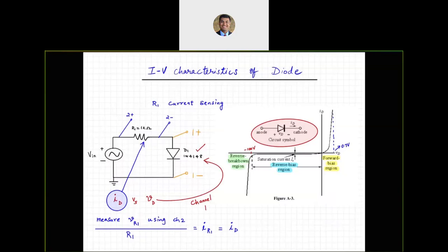The question is: subtract the threshold of the diode from the circuit's voltage, then calculate the current in the circuit using the remaining voltage. Yes, that's exactly right. So the turn-on voltage or the threshold voltage of your diode, if that is 0.7, that is going to be the case when it is one diode.